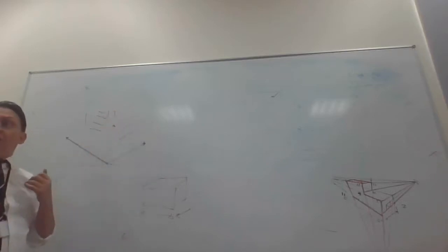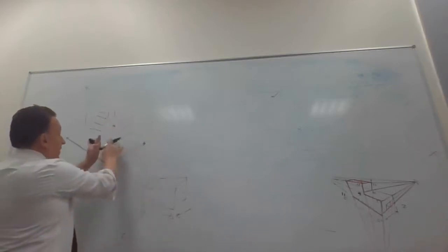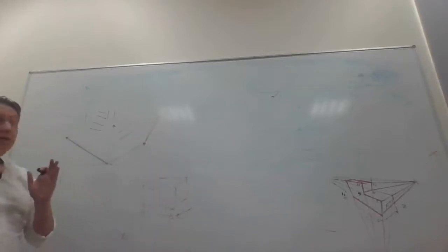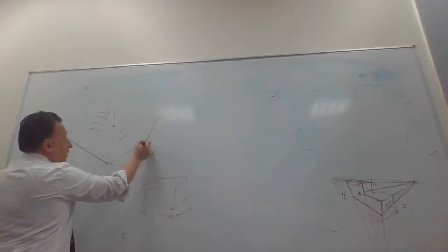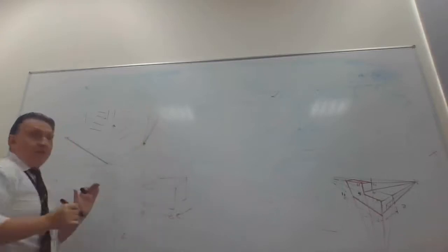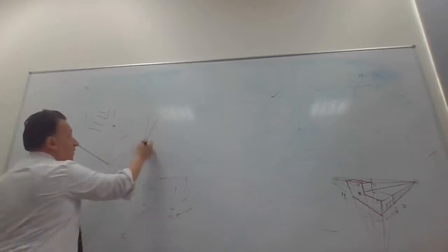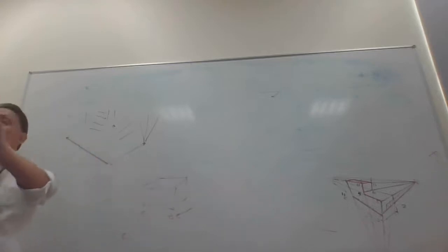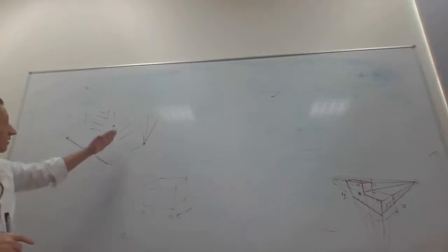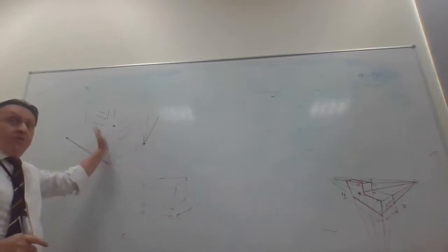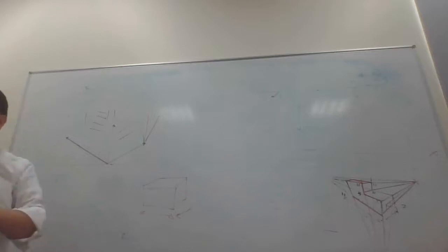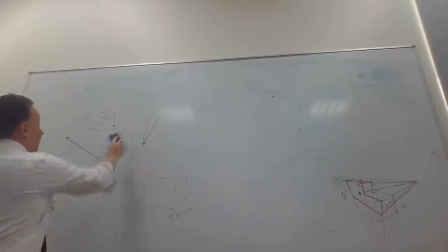One of the mistakes I found with the students, when they want to draw the end of this line here, they draw it like this. No, you have to keep it parallel to this one. See? If you draw it like this, it will be better. Vertical. If you draw like this or like this, it will be a mistake. Okay? So we only have 3 types of angles. Either right, 30 degree, left, 30 degree, or vertical. You don't have 45, 60, 20. You don't have. Okay?